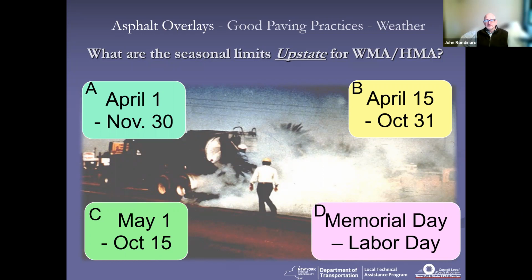Great. And then the other one, what about applying tack coat between the fresh binder and top course in a single paving operation? It's not required, and some people do it and some people don't. I would say it depends on how long you've got between. If it's just a few days, it's one thing, but if it's a project where you've been a month or two, I would put tack. Absolutely. If you've wintered that surface, you've got to put a tack coat down. Even if you've got a month or even a few weeks. I don't disagree, but clearly you're going to be required if it's wintered. But I'm with you. Once it's been there for more than a little bit of time, you've got to put the tack down.